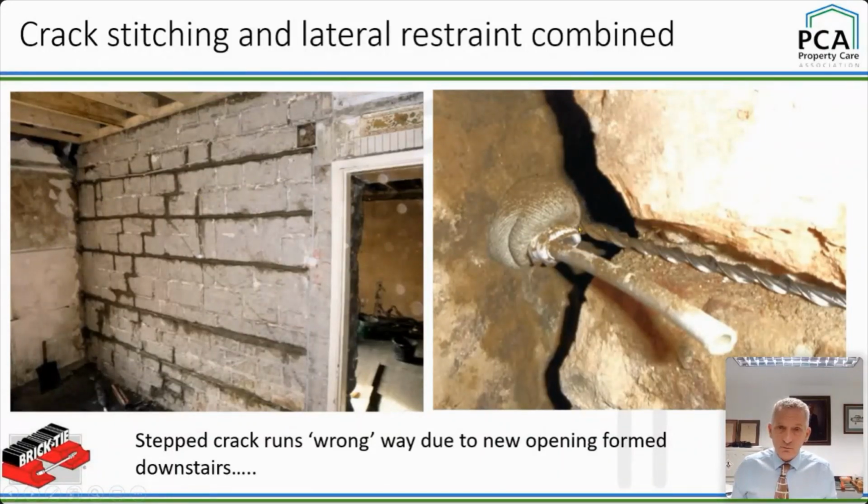which is the left one. So what we've done is that bar actually has been passed down a big diameter hole into the outer leaf, and then a sock anchor, something similar to this. I know it's got a piece of rubble through it where it bonded that, is inflated afterwards, so it grips it. So that's just that.